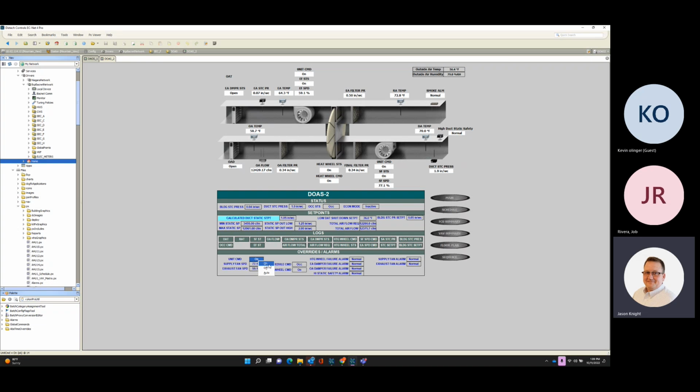Okay, so great question. And it's going to be this unit command point. There is no start, stop, occupied command with this. It's a unit command. This unit will not run unless this single point is commanded on. And what this does is this activates a binary output on the controller. It then energizes the outside air dampers, whether they're 0 to 10 or they're 24 volt on or off.